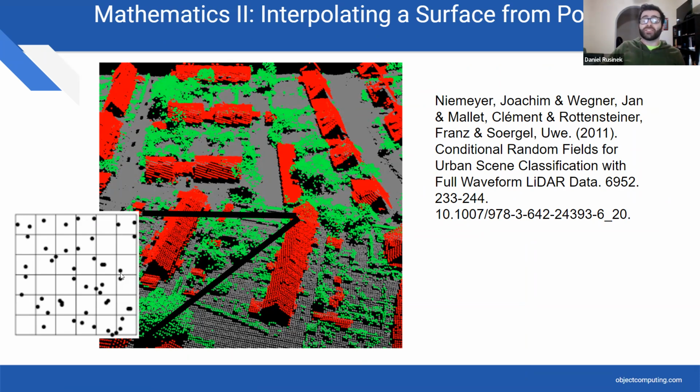And really, these are essentially all GPS points. They're all relative to the receiver. So it's really important that you know where your receiver is, because the only thing that you know other than the position of the receiver is how long the laser took to reach a point and return. And then you can figure out the point relative to the receiver from there. So if the receiver position is off, then everything is off. So again, the GPS is incredibly important.